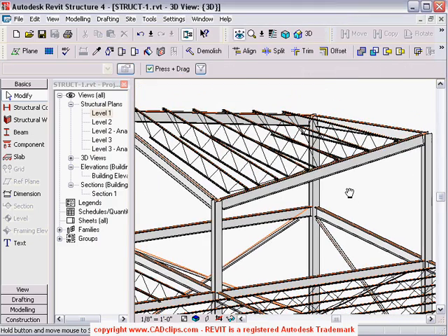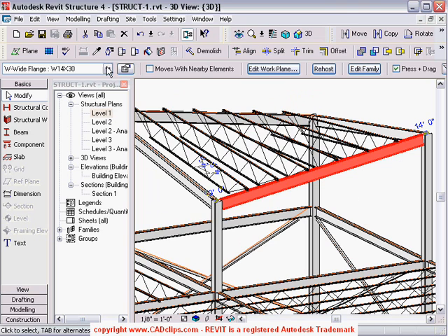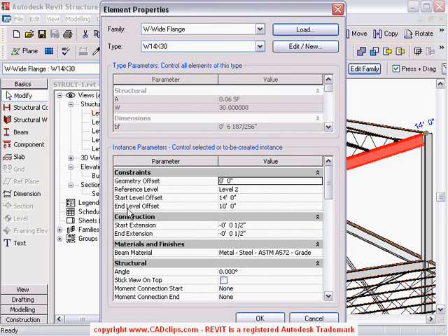Okay, I can also take this particular beam and go in and have a look at this and say, you know, there's a 4-foot offset. Well, if I bring this down another 2 feet and say it's only 8-foot offset from level 2, that will slope, and then we'll also see my beam system and all my joists will slope on top of that. They'll fix themselves up, and you can see that my recording software is also slowing me down here a little bit.